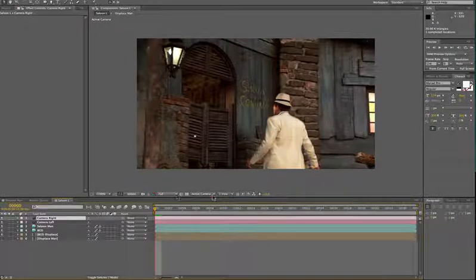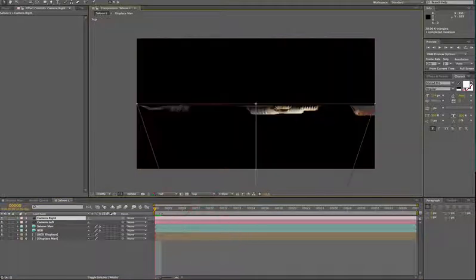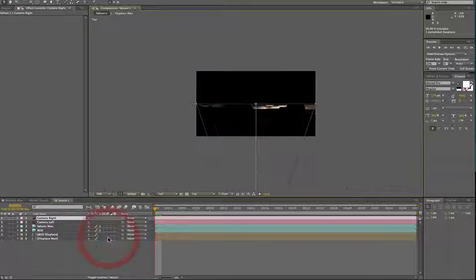views. So if we have a look at the top down, for example, you can see my camera selected here, and I'll just zoom out a little bit, let's say 50%. At the moment we're looking dead straight onto the scene, but eyes often don't look at a scene that way. Our eyes are obviously right next to each other in our heads, but when we're looking at objects we often look into the scene, and our eyes cross in and converge. So having a two-node camera helps us control how those eyes slightly converge in, and I'm going to do that